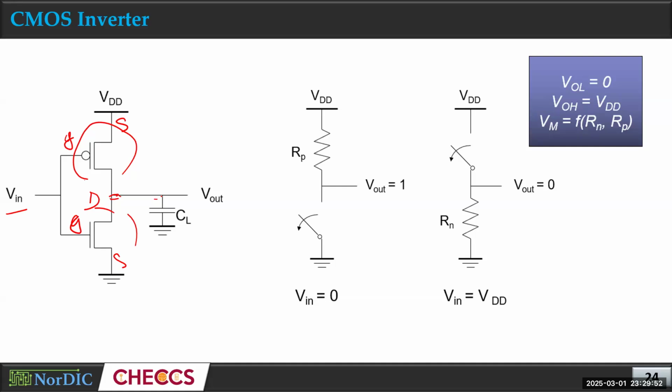As I mentioned, with CMOS we are only considering digital circuits so far. In digital, we have only two types of inputs, right? Logic 0 and logic 1. We cannot have in-between values. That's how the computer works. For logic 0, the input is 0 voltage, and for logic 1, the input is VDD, the supply voltage or the highest voltage that we can use. I think you remember these things.